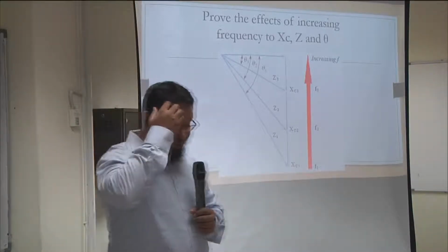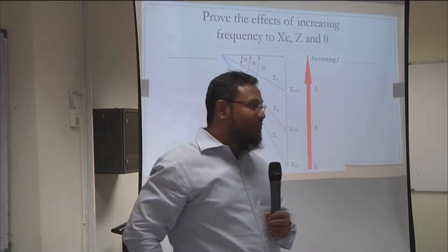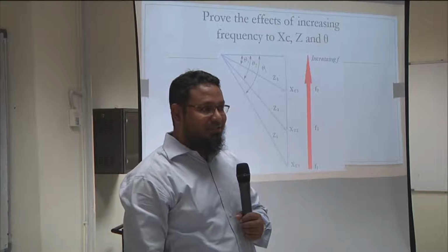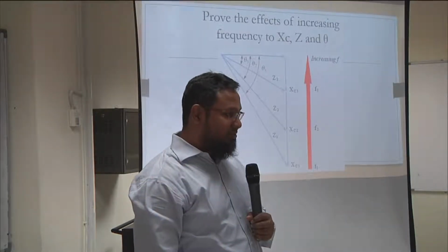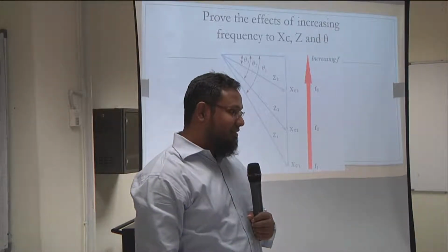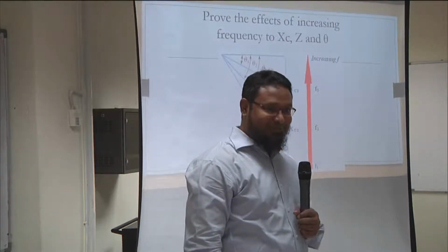So in other words, the capacitor will behave like an open circuit whenever the frequency is 0. Do you know when we have the frequency as 0 in case of power supplies? The DC. DC has a frequency 0.